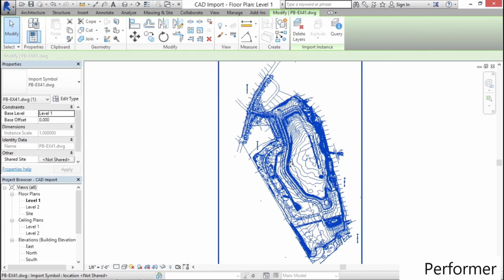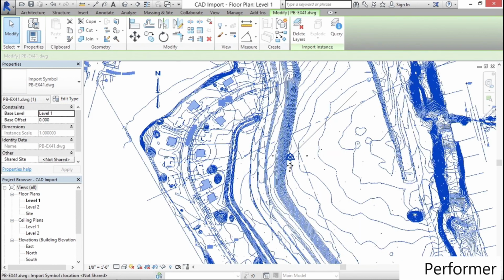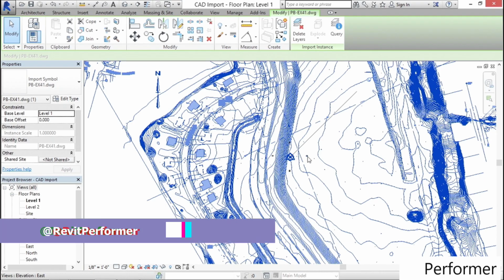And somewhere here in the middle, we can see our project base and survey points, and you can see our elevation markers over here. So it is a fairly large file still, but still well within the required 20-mile radius, and it didn't generate a warning, right? The trouble is, if you start querying the coordinates and the locations in this file, it doesn't match what the civil engineer has. And so that might be a problem for the project team.